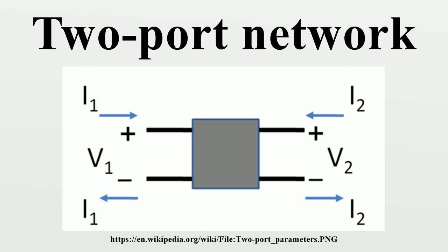Series-parallel connection: when two ports are connected in a series-parallel configuration as shown in Figure 14, the best choice of two-port parameter is the H parameters. The H parameters of the combined network are found by matrix addition of the two individual H parameter matrices.